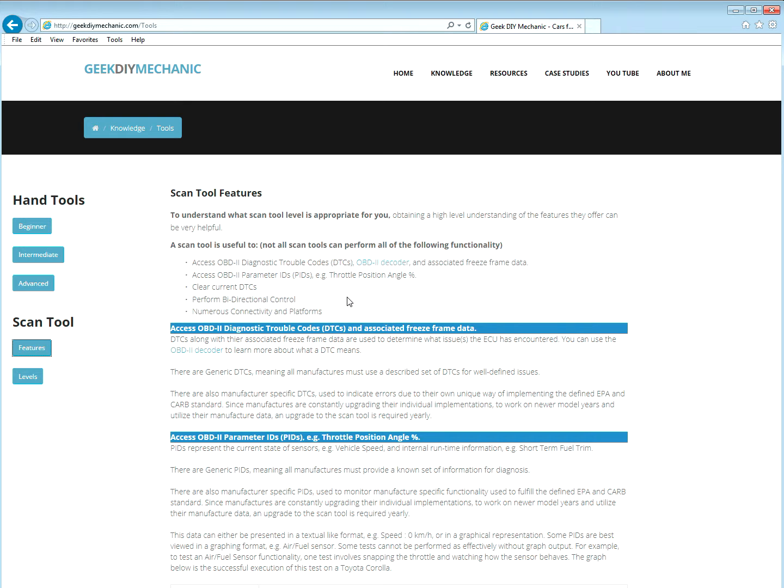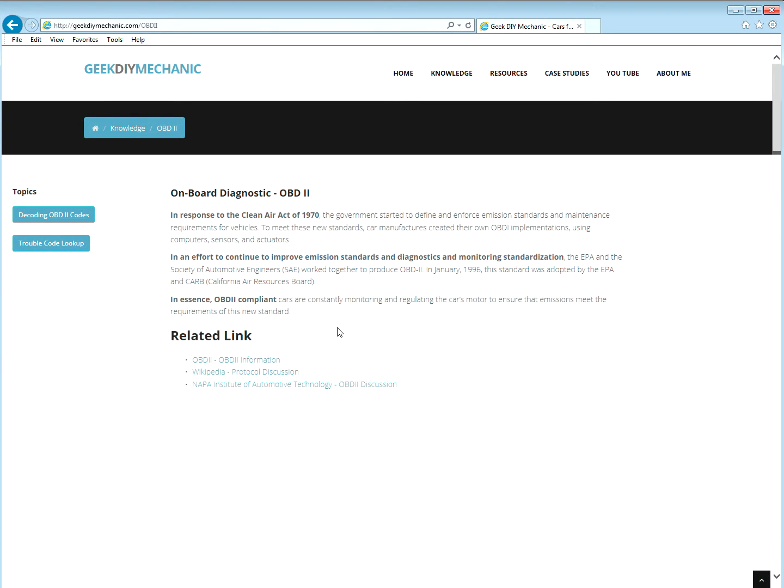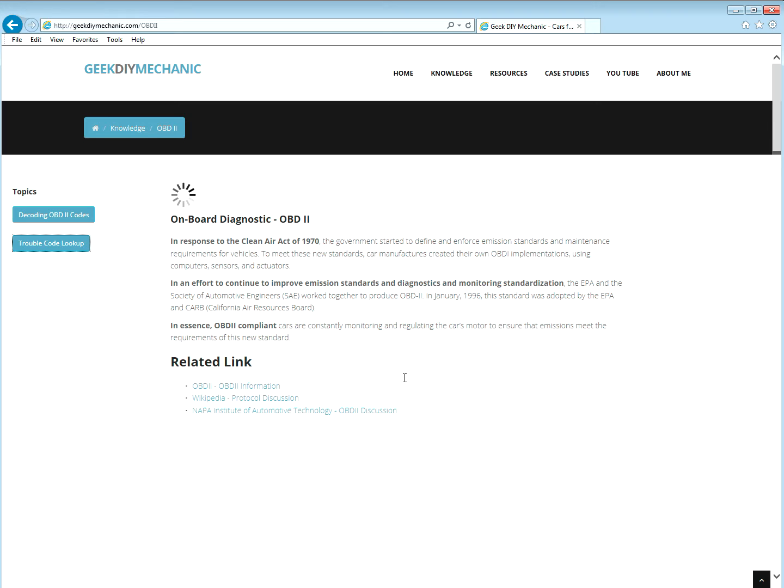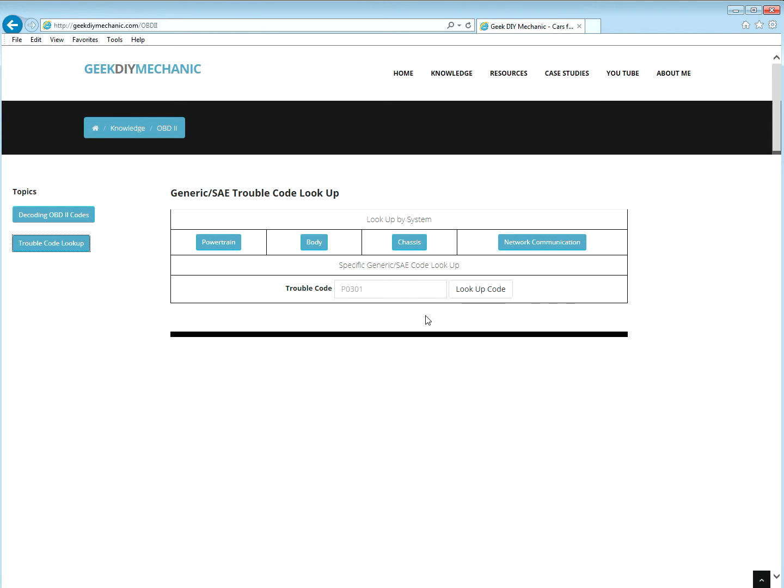Maybe it'll tell you engine load, engine temperature, things like that. And then once you get that code, let's say P0171, which is a lean code, you can go to a decoder, or the scan tool can have information about that DTC.